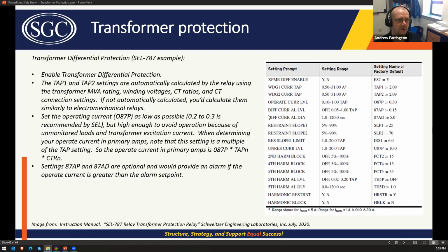You'd be surprised how often that happens, because they'll test it based on what you tell them the settings are, right? So you say it's a DY1 transformer, and they'll run the test setup for a DY1 transformer, but because of the primary phasing, it's actually DY11, say. So when they go to put it in service, everything tested right when they tested it. It's not necessarily their fault.